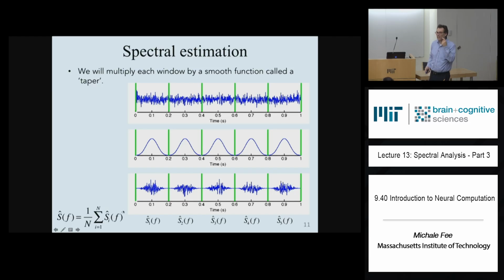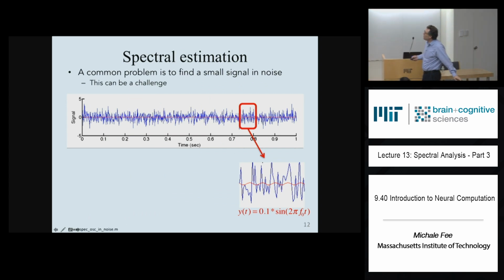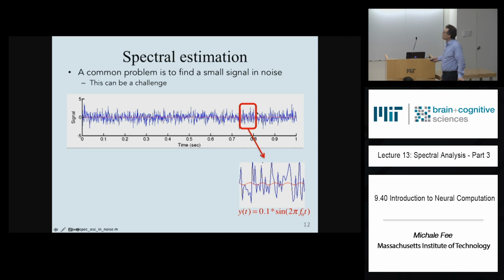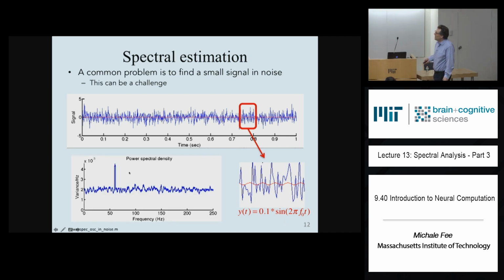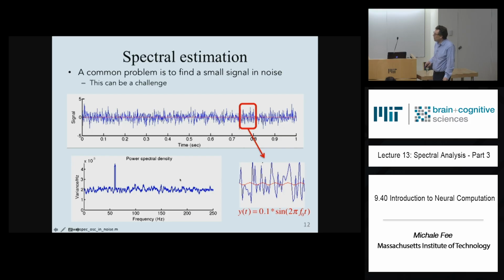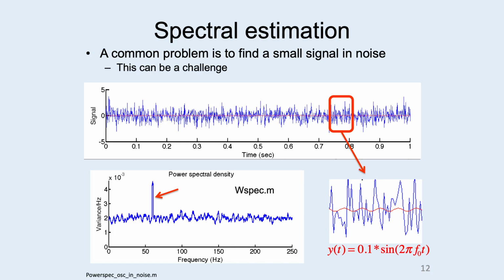Any questions? Okay, again, that was review. And I showed you briefly what happens if we take a little piece of signal. The blue is white noise with a little bit of periodic sine function added to it. If you run that analysis, you can see that there is a large component of the spectrum that's due to the white noise. That's this broadband component here. And that sinusoidal component gives you this peak. And I've posted, or Daniel's posted, a function called wspec.m that implements this spectral estimate.